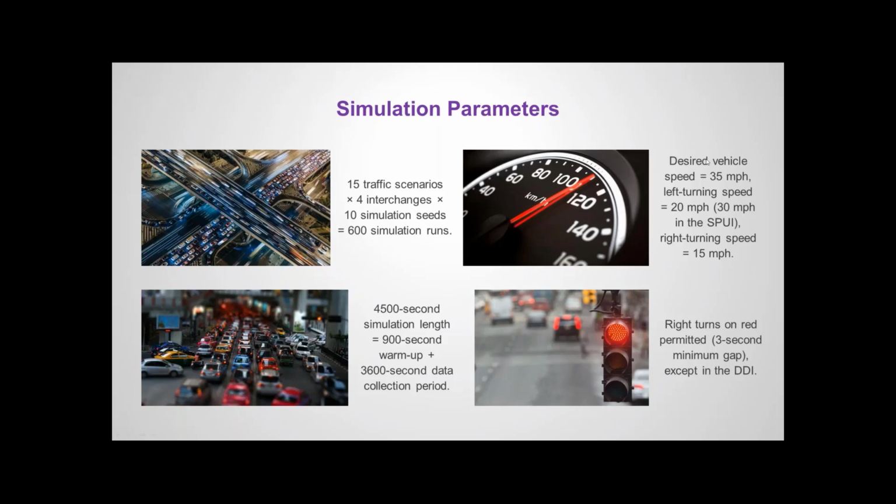Also, here are my desired speeds, and also I ran each simulation for 4,500 seconds, 900-second warm-up, and 3,600-second data collection period. And also, of course, right turns on red were permitted, except in the DDI, since it's recommended by the DDI informational guide not to do so.